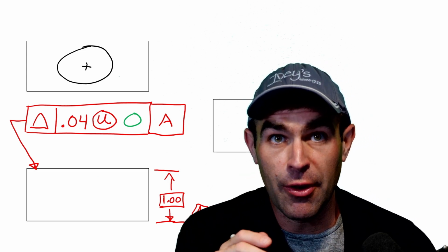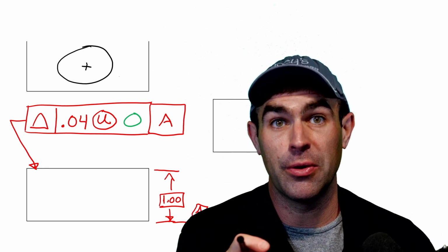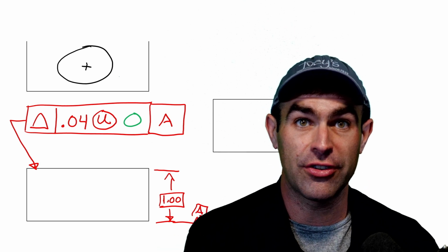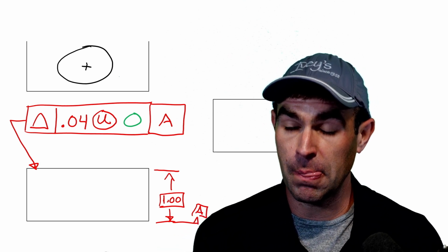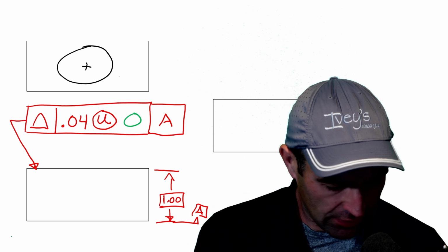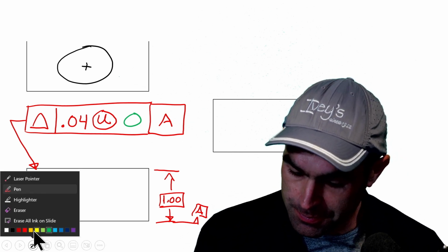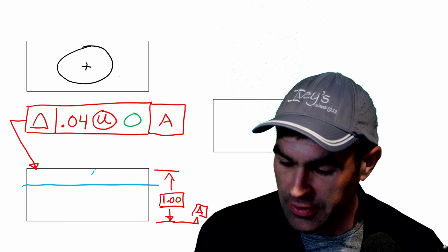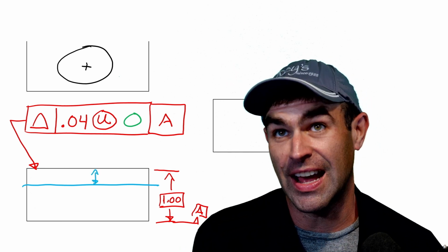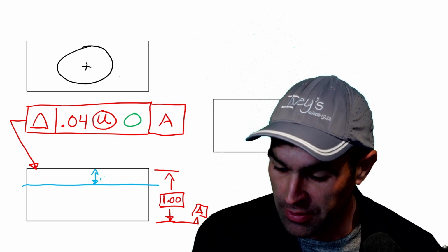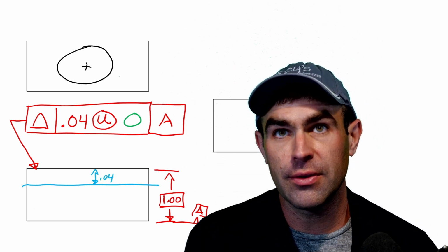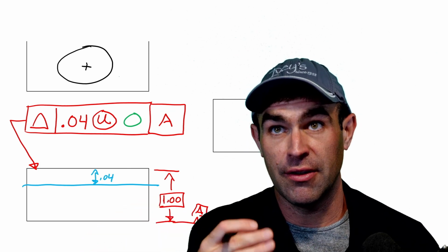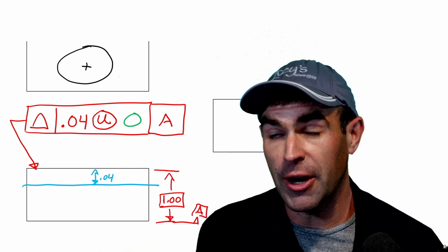Now, let's read this out. We've got a profile, 40 thousandths, unequally disposed. 0 of that 40 thousandths is in the direction that would add material. So in our first example down here, we're going to shift our tolerance zone this way, right? Totally inside of the true profile. Here's our 40 thousandths, and we can calculate our MMC and LMC, or upper and lower limit, from there.